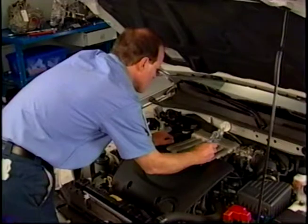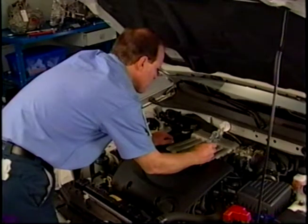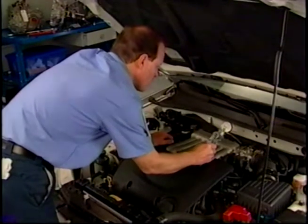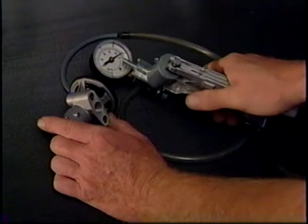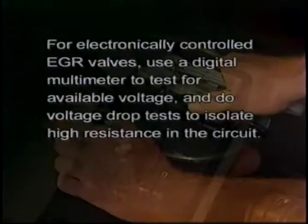Using a vacuum pump or scan tool, depending on the application, open the EGR with the engine idling. The engine should stall. If it doesn't, the valve is inoperative. If the signal to the EGR to open is present, remove the EGR valve and check for a bent shaft, bad diaphragm, or a carbon buildup that is restricting flow.